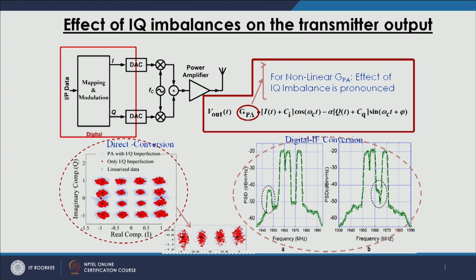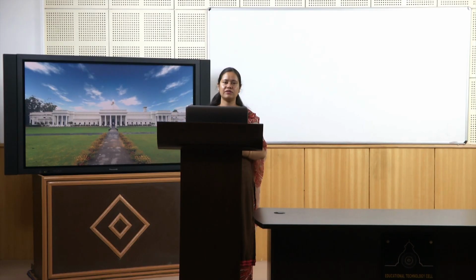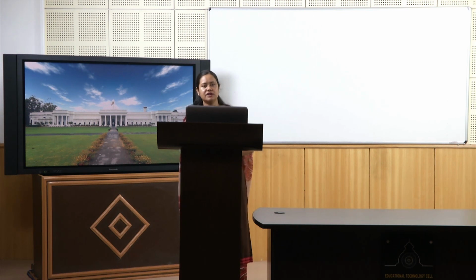What will be the effect of such a system in the transmitter when the PA is also there? Of course, when we discussed earlier, we were not taking this PA into account. The distortion which is coming from the modulator, when it passes through this power amplifier, becomes even more prominent there. The distortion level has gone up a notch higher than what it was supposed to be earlier.